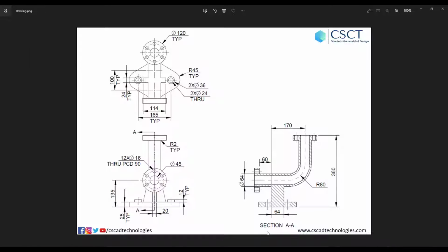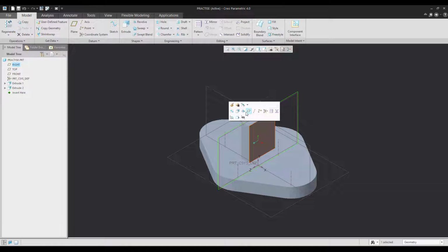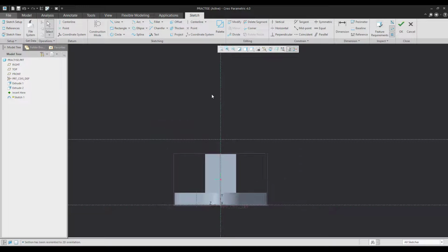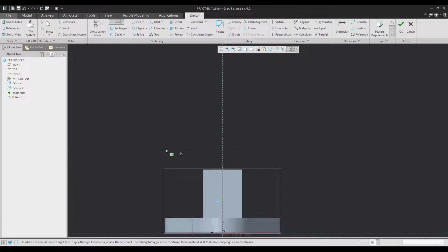Now, the shape, as you can see this way, cannot be done using any extrude or revolve command, but it can be done using a sweep command. Sweep always requires a path first. What your profile is supposed to follow is more important. So let us try to make this path and then continue making our profile. This is the center for the path, and then I have a line, and then I have a line, and then joining these two is the arc.